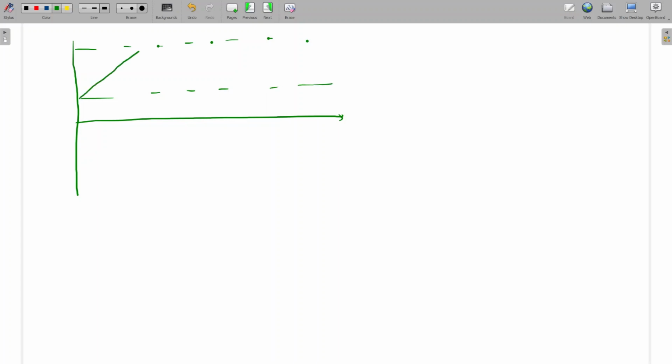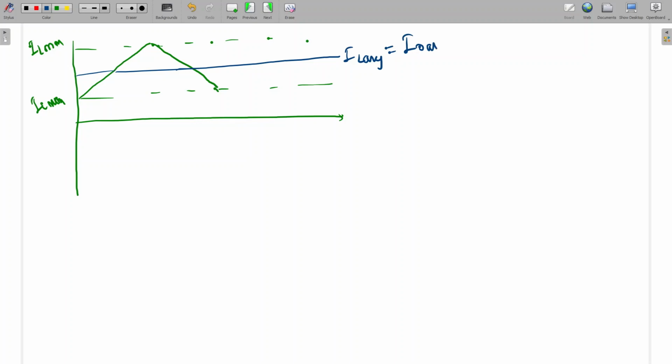It will charge like this for the on duration and then discharge, between IL max and IL minimum. And what will be the middle value? The middle value will be the IL average. This value will be the I naught average. So how much will it be? 25 amps.